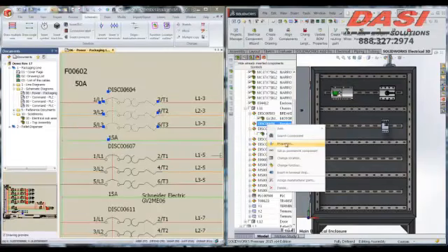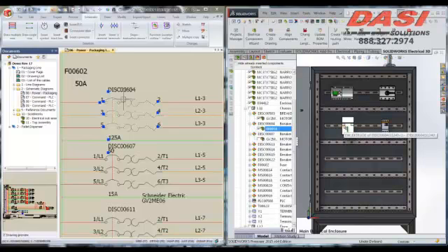The mechanical engineer can actually put in the device, if that is what is required, just by selecting through our libraries. And again, like I mentioned, some of this you have already seen in a previous webinar, but I just wanted to go through it again. You can see that the schematic process is updated and accurate based off of what is showing as far as the visual checks. But once you have that manufacturer, you can do one of two things. You can insert the 3D model that might be assigned to the device. If there's not one assigned, it will pick a generic device and resize it to the dimensions required from the manufacturer's properties.